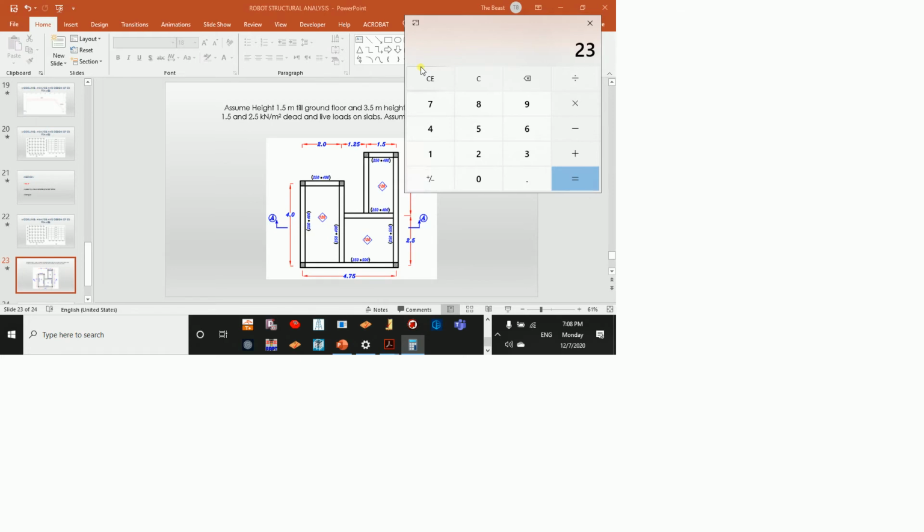We cannot use the density. A lot of people are using the density, but I'm against using the density. Now you are talking about hollow blocks. Your hollow blocks are not the same all over. You cannot assume the same density all over. So the mass of one block is around 23 kg. From where will you get it? You will get it from the factories. So the typical mass is 23.